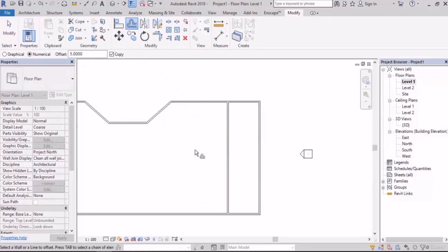The other trick is that when you offset this one, for example, 5 meters, it offsets the other one half of it. And it does it because it wants the new space you create not to get involved with the walls. And also it does this only once, so if you delete it, it won't do it anymore. You see, just like that. So when you delete it once, it's like you tell it not to get involved. I know what I'm doing. And then you can go on with your work. So remember these two tricks about offset.